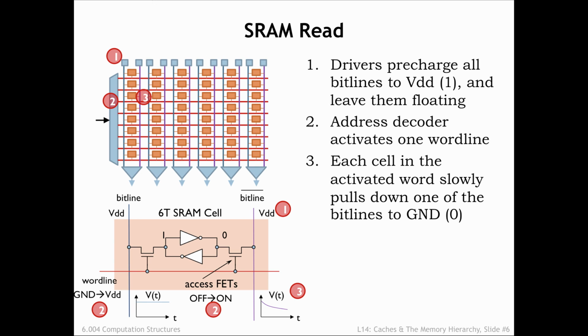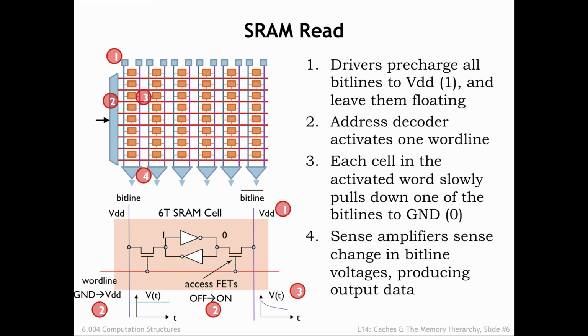Transitions on the bit lines are slow since the bit line has a large total capacitance and the MOSFETs in the 2 inverters are small to keep the cell as small as possible. The large capacitance comes partly from the bit line's length and partly from the diffusion capacitance of the access FETs in the other cells in the same column. Rather than wait for the bit line to reach a valid logic level, sense amplifiers are used to quickly detect the small voltage difference developing between the 2 bit lines and generate the appropriate digital output.